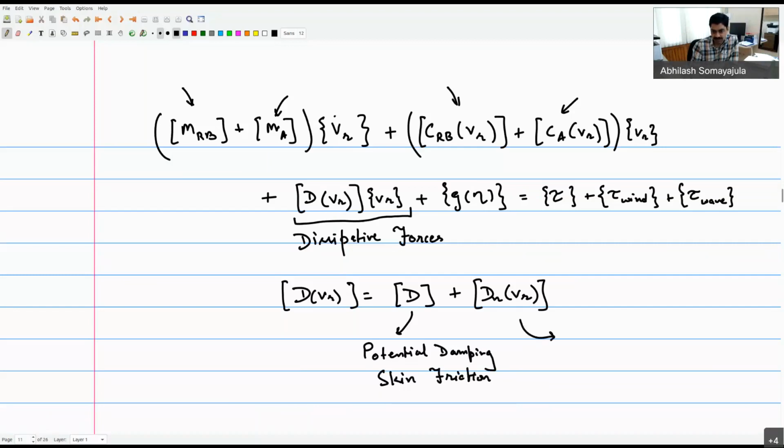And what was the nonlinear part coming from? Turbulent boundary layers, yes, not laminar. Because of the nonlinearity, it was coming from the turbulent boundary layer. What else? Wave drift also came into the nonlinear part, right? Those are some of the things causing the so-called nonlinear damping.